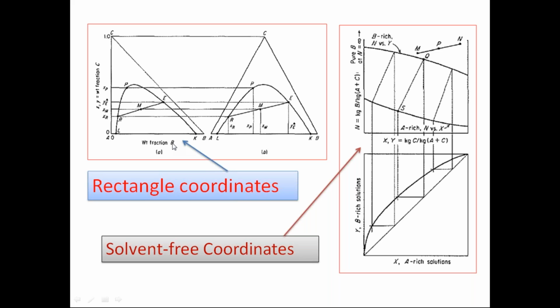So that gives the weight fraction of the solvent which you are intentionally adding, the extracting solvent. So you will get this. A similar type of curve can be reproduced on the ordinary graph, because drawing the triangle diagram is a little difficult. Then you can draw in this.